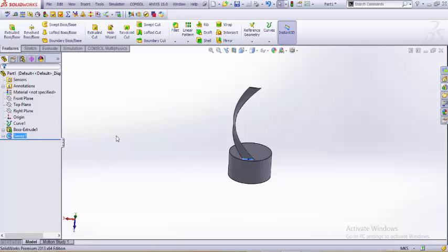Now we produce another top surface that would hold the blades together, because if it doesn't hold it together, these tips would always tend to bend when the fluid is flowing through this, and this would always cause a moment about this fixed surface, and at one stage would cause fatigue failure to these blades. So for that we need to fix this surface as well.